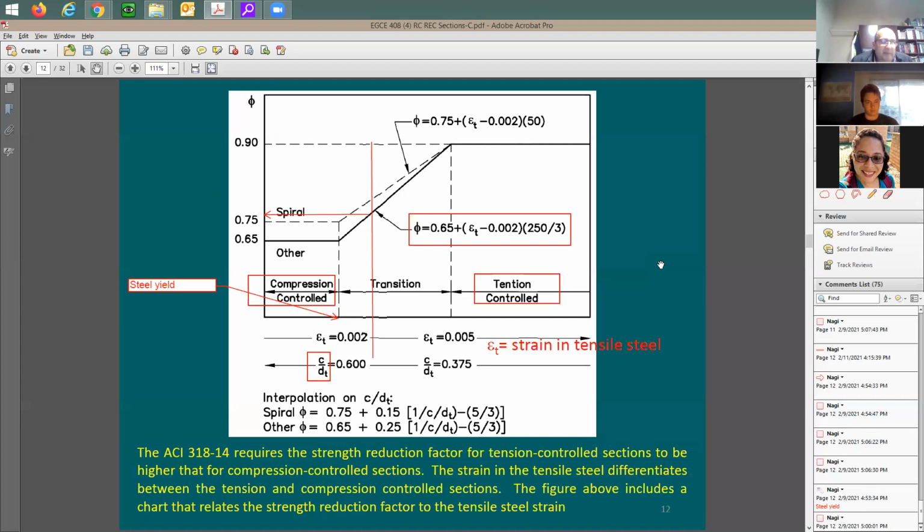So if you have a beam and you don't have enough reinforcing, in some cases the solution is just to add some reinforcing, and then you can achieve the strength you wanted. In some other cases, you add reinforcing and it is not working out because you're chasing your tail. You add more reinforcing, so the tension force goes up, but at the same time, the phi factor is coming down. This should be like an optimum design. With a given cross-section area, there is a best amount of reinforcing to put in. It's not just adding reinforcing, adding reinforcing. You see my point?